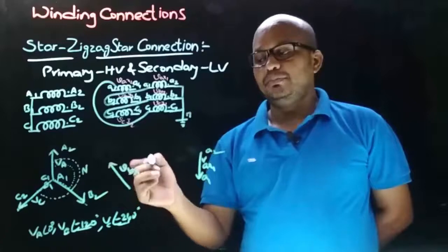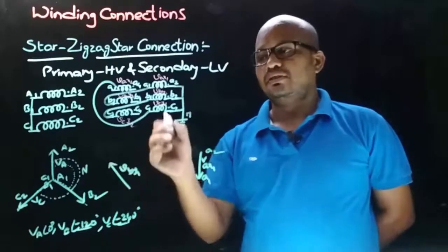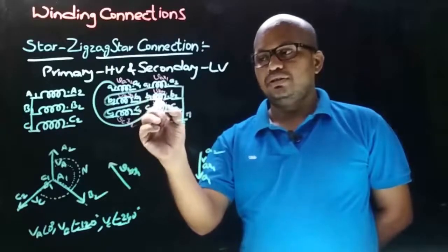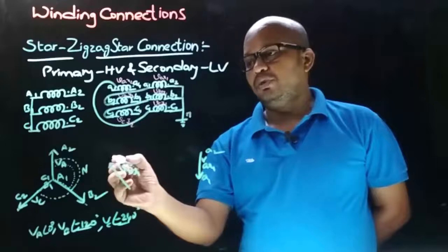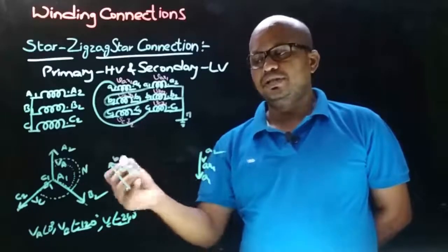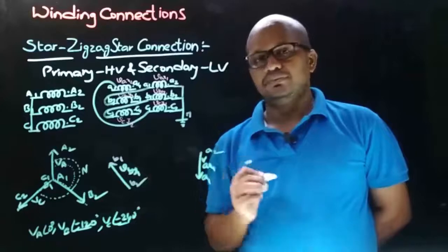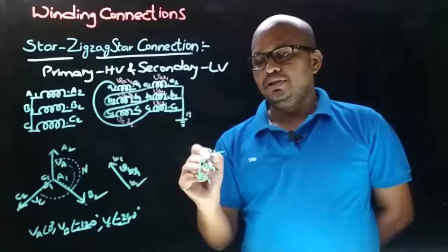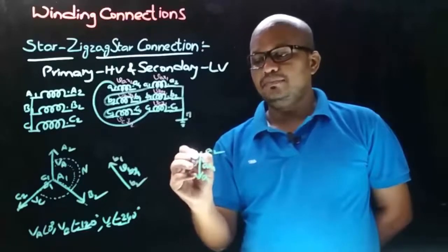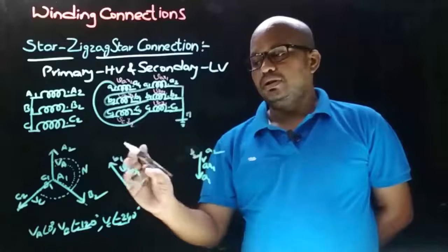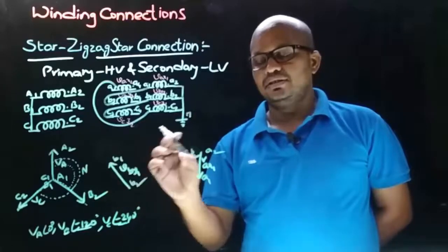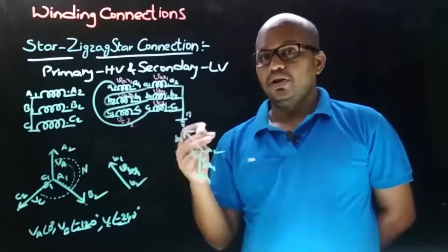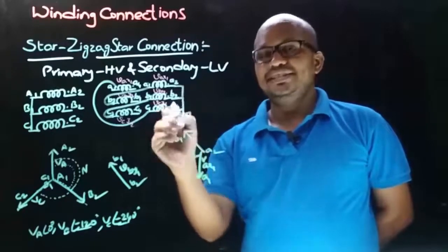And now we need to decide the terminals of the secondary side VB Y1 phasor, and here the terminals are B1 and B2, and as the connection is taken from the non-dot end, that is B1, the arrow will point towards the connection we took from, that is B1, and the other end will be B2. Now coming to this winding connection, A2 has a B2 connection, means here in the phasor diagram to A2 there must be B2. Therefore draw this VB Y1 phasor such that A2 will have the B2 connection. So like this.